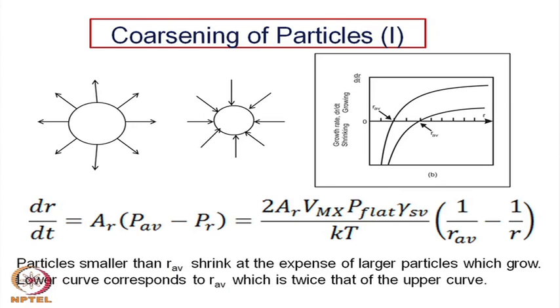After the intermediate stage sintering is over, there is a possibility of grain growth, sometimes called abnormal grain growth, a very fast rate of grain growth of certain grains. Not all the grains grow, of course; only a few grains grow abnormally, and their size becomes an order of magnitude larger than the other grains.